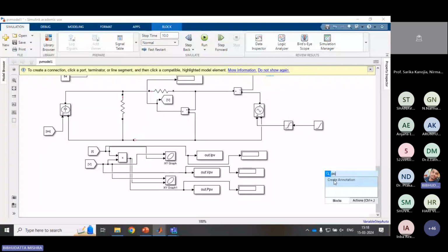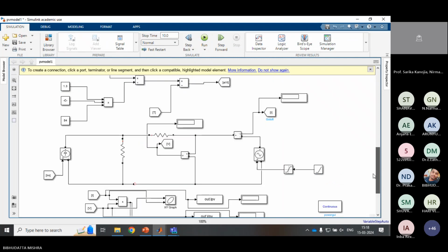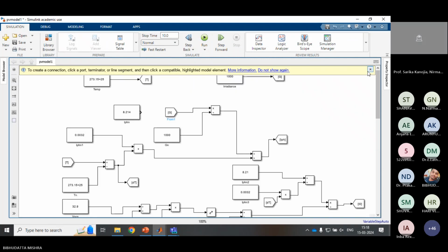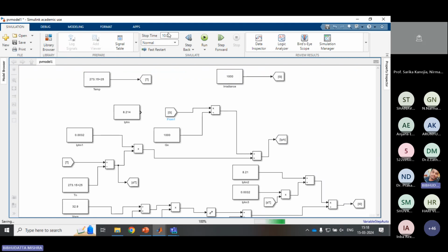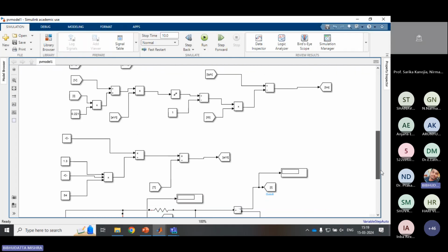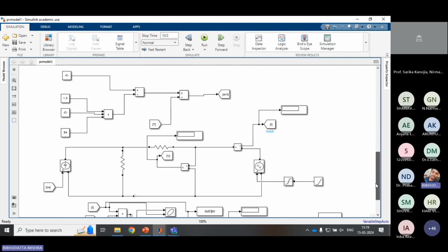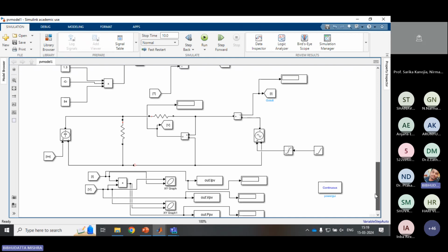Now on for the simulation time, let me summarize the same thing. First of all, I declared the values for temperature and the irradiance, then went for the modeling of IPH, then modeling of I naught, then modeling of IM. Then how to get the value for output, two variables voltage and current. Finally, we are plotting the IV as well as PV curve.